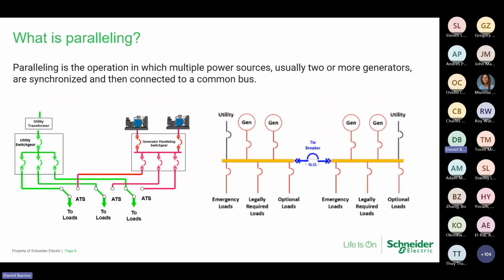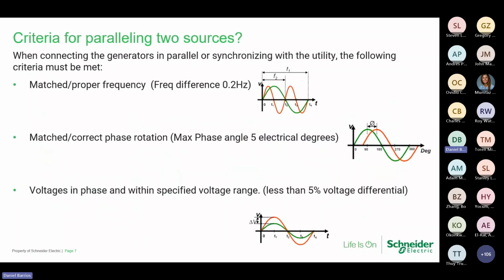In doing so, we're able to close that first generator on either side and meet that requirement. Once all generators are online and all of the transfer has been taken care of, then we will start evaluating how many generators are really used. Keep this picture in mind, because as we go into some of the reasons that an onboard paralleling may not operate, we're going to point out that they do not seem to operate quite well using a tie breaker.